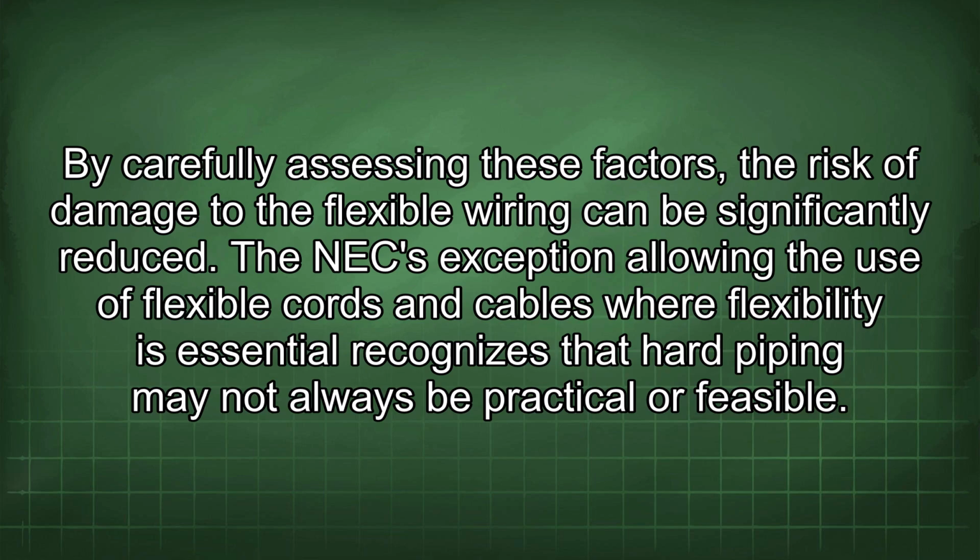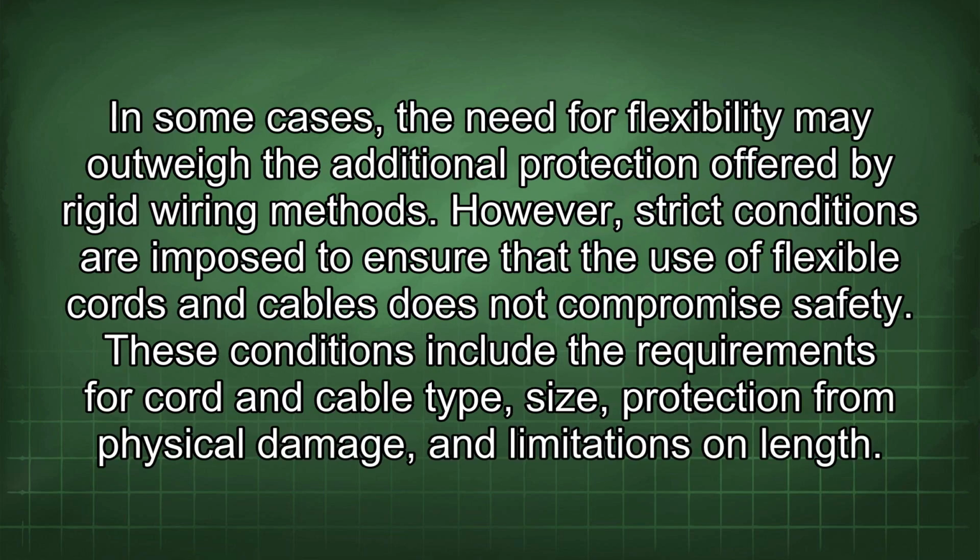The NEC exception allowing the use of flexible cords and cables where flexibility is essential recognizes that hard piping may not always be practical or feasible. In some cases, the need for flexibility may outweigh the additional protection offered by rigid wiring methods.